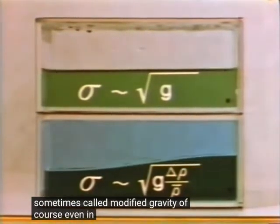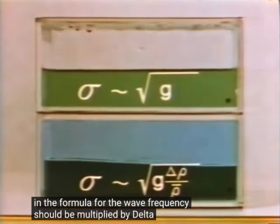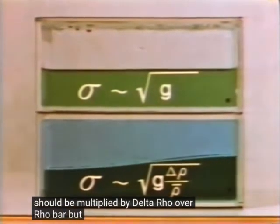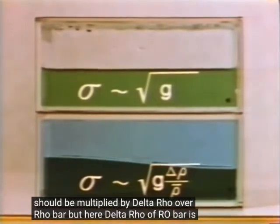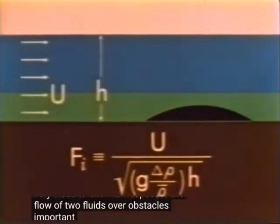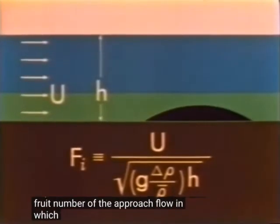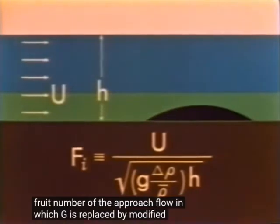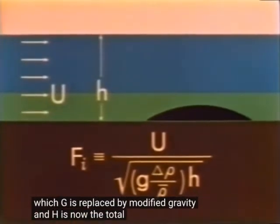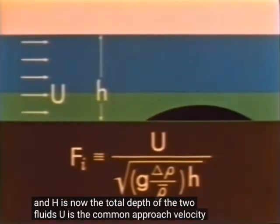Of course, even in the water wave case, the G in the formula for the wave frequency should be multiplied by delta rho over rho bar. But here, delta rho over rho bar is very close to 1. With respect to the flow of two fluids over obstacles, the important fluid number is now the internal fluid number of the approach flow, in which G is replaced by modified gravity, and H is now the total depth of the two fluids. U is the common approach velocity of the two fluids.